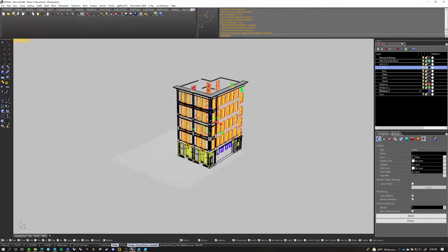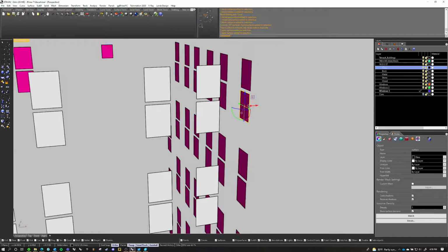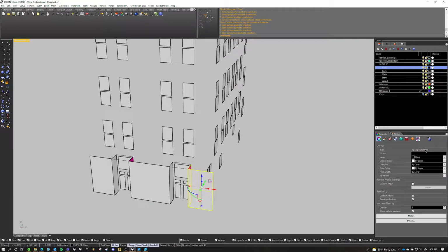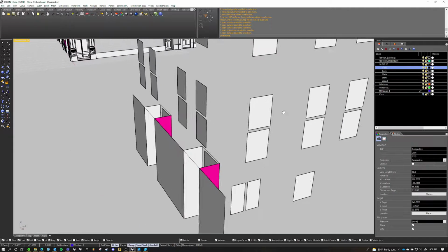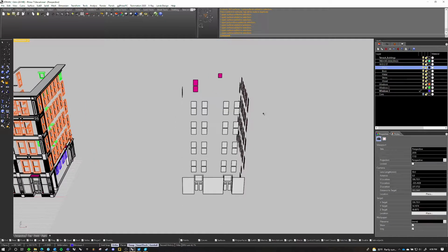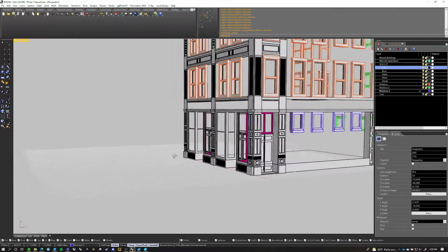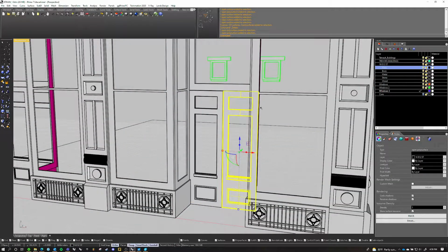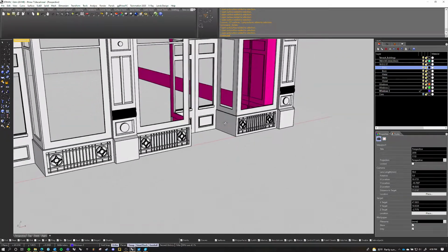Select objects. You can see that all of these are either surfaces or, let's see, open poly surfaces over here in type. You can see all that info, surface, all that stuff. We don't want any of that, so I'm just going to get rid of it. And what we're left with is kind of the bones of the building. These are still open poly surfaces, which is frustrating, but we can fix that.